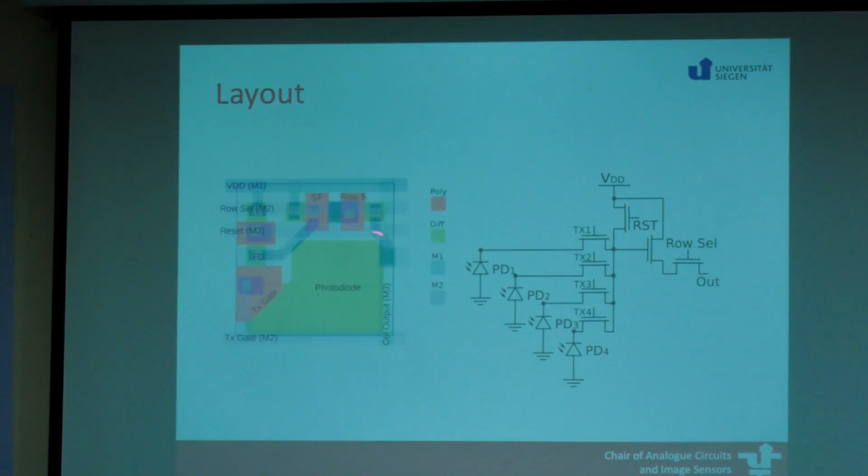To some extent the limitation is, if I have 4 pixels, a pixel here and a pixel here, then they all 4 can share this circuitry, or else you have to run a long wire from this central circuitry to the pixel. And you don't want to run that, because you've got a very small amount of photo charge generated. You don't want to move it over a long distance, you will start losing it. So 4 or 8 generally, people don't go more than that.